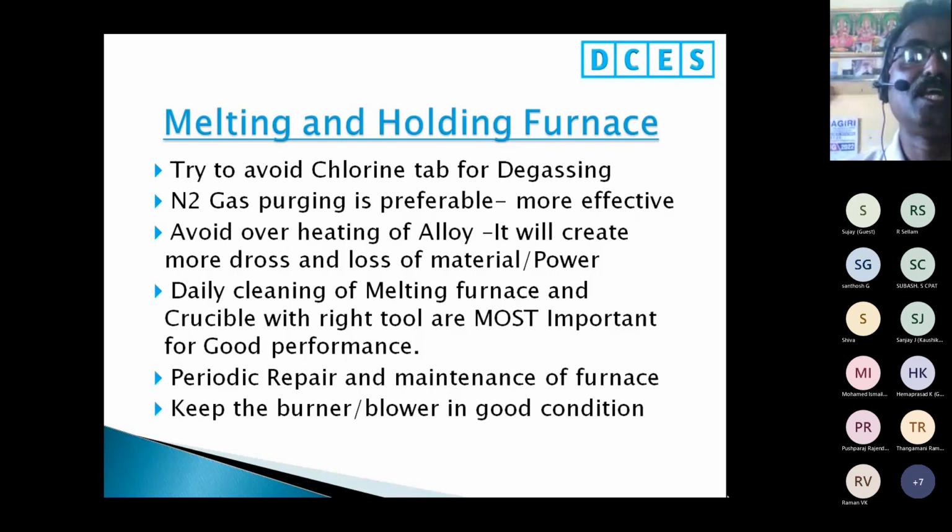Daily cleaning of the melting furnace and crucible with the right tool is most important for good performance. Daily cleaning should happen in the melting furnace. Otherwise, what will happen? The aluminium oxide will deposit on the wall and become corundum. It will mix with the aluminium and create a hot spot. So the daily cleaning should be inspected, even sometimes by top management.